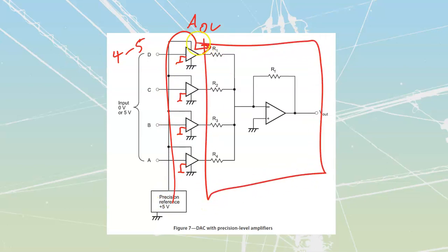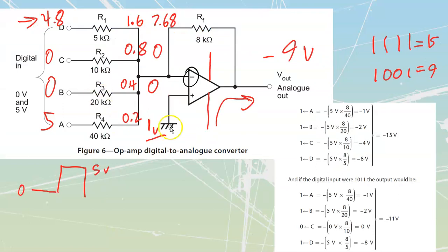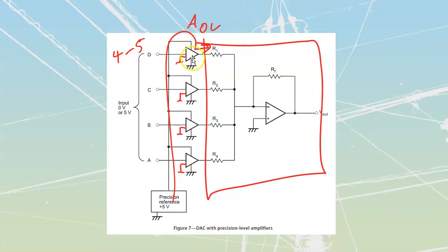From here on down, it's the exact same circuit as this one that we were looking at, our figure 6. All we're doing is we're just putting in those precision modules and using other op amps ahead of it to drive us out to a proper full 5 volts. That way we can take janky signals in from other stuff that's going to be out in the field that might not be going all the way up. The high in the field might be a value ranging all the way from 3 to 6 volts, and my low might be something that's going to be smaller inside of there. So what I can do is I can take that 3 to 6 volts anytime I'm in that range, provided that I set these ones up right. It's going to read that properly as a high and provide that full 5 volts that we would need off of it.